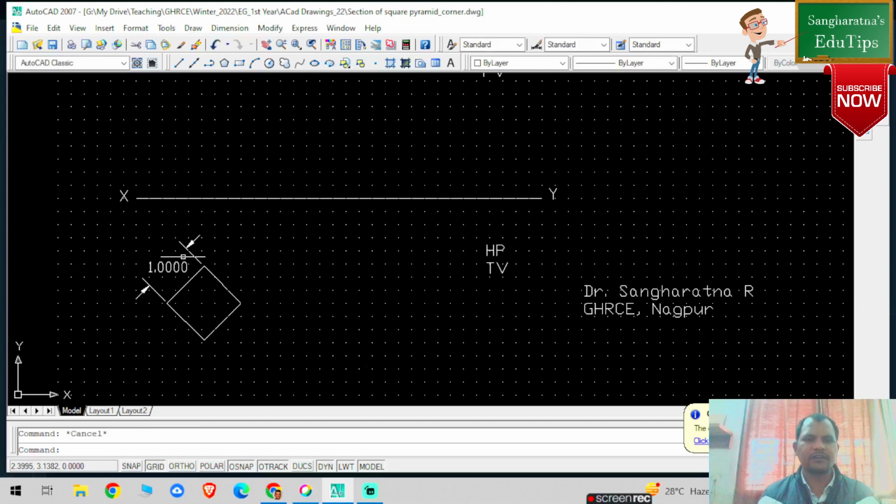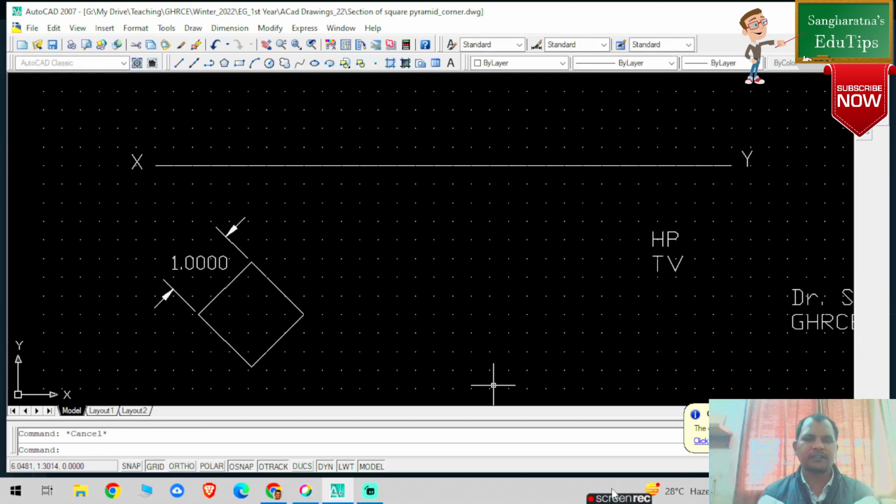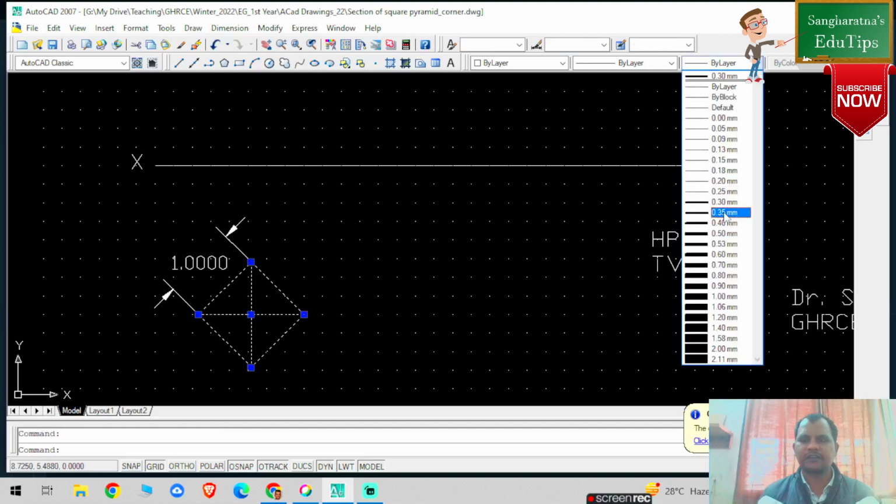And then I'm going to draw the center of these, from this particular point, selecting this line, press escape. In the top view I can see the base of the square pyramid as well as the slant edges. So I'm going to convert this particular line into thick color, because it is visible, right?